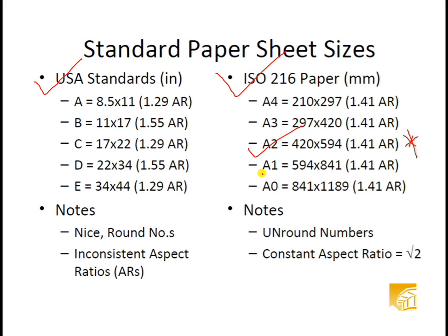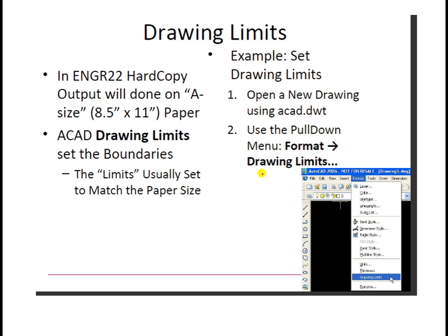In engineering, that may be mechanical also, they will be using these if they have to draw the detailed drawing as well as assembly drawing with all the details in industries. Drawing limits you need to set. Why drawing limits? Because if you are going to select the template, then there is no need to have these limits because the template already takes care of that. But if you are not going to select the template, then you need to select the drawing limits, and inside that particular limit only your drawing should be included.